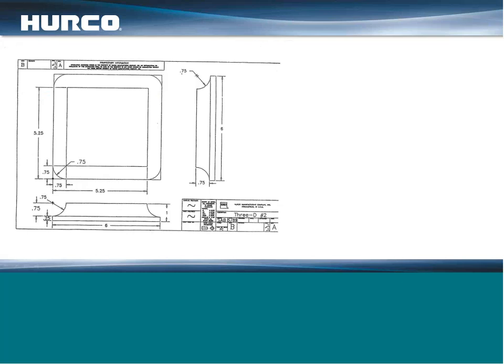Because of the limitations of only being able to translate in Y, typically you'll find yourself using swept surface for anything that looks like this, where you're going all the way around multiple sides, and typically using 3D mold for anything that you want to rotate around. If you want to rotate around the x-axis, you're still going to have to use that 3D mold. But for anything else, you'll probably find yourself going towards the swept surface.